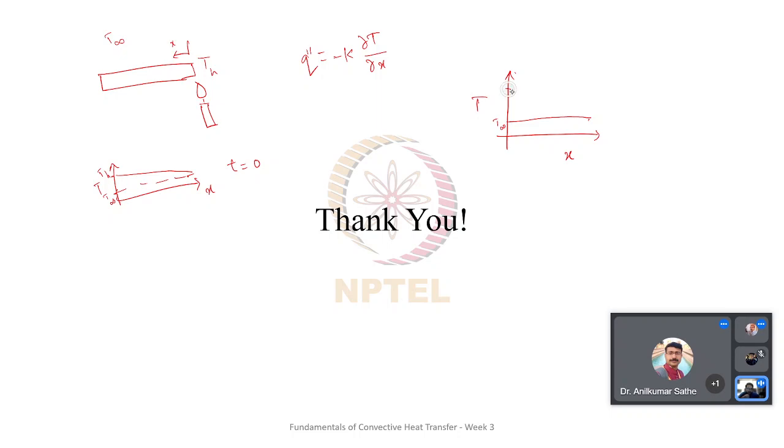Initially this part heats up, and then slowly this temperature profile develops over time, and finally it becomes a uniform temperature profile, and this gives us the required dou T dou X. This takes some finite amount of time in reality, but Fourier's law assumes that this temperature gradient is set up instantaneously as soon as heating or a temperature is applied at any location. Does that clear things up?